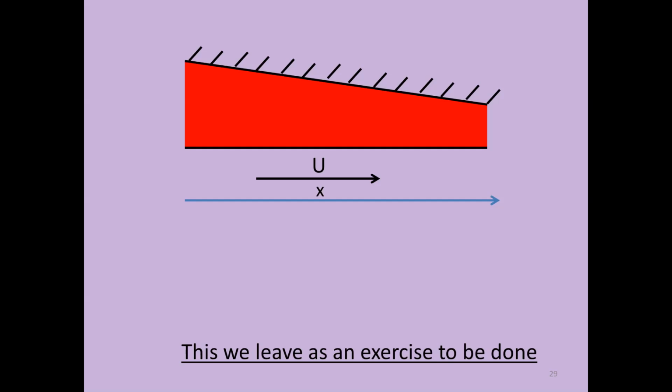Now, since the fluid has a viscosity, as the lower surface moves towards the right, the fluid is going to have a tendency, because of its viscosity, of being pulled into the converging gap, because of which pressure is going to develop.